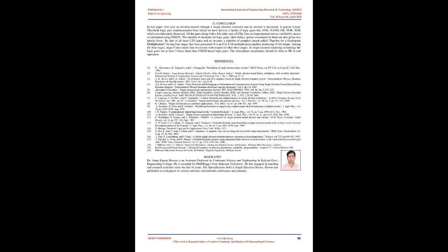If the error probability is assumed to be 10 to the power of minus 15, then the delay for the inverter will be 2.3025 ns, and similarly the other delays for the other gates can be calculated as shown in Table 3. And it is clear that the TLG-based circuit must be faster than the SET-based circuit when.